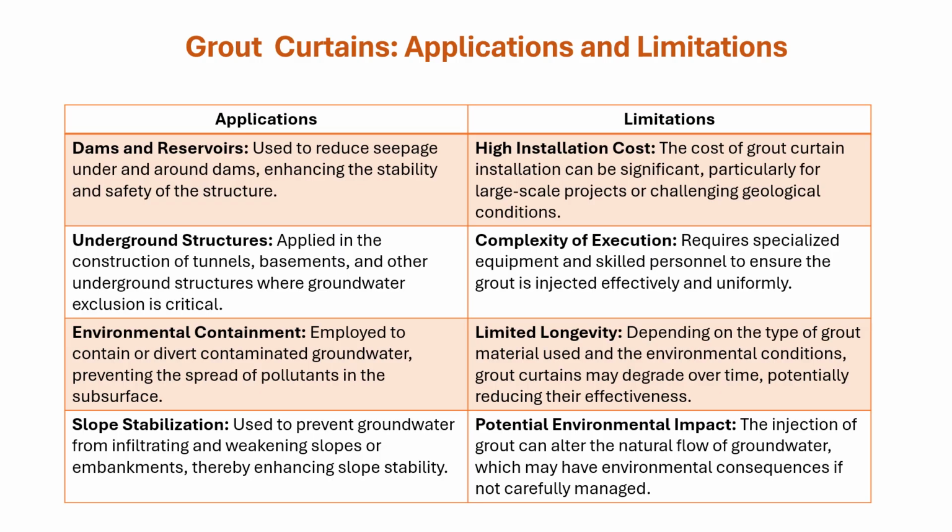As with other permanent dewatering systems, they have high installation costs. They are not easy to install and execute. They have limited longevity, and this is very important to remember. That's why their quality may degrade over time, and thus their efficiency may decrease. They may also have a potential environmental impact, because the injection of grout can change the natural flow of the groundwater, which has many environmental consequences that should be carefully managed.